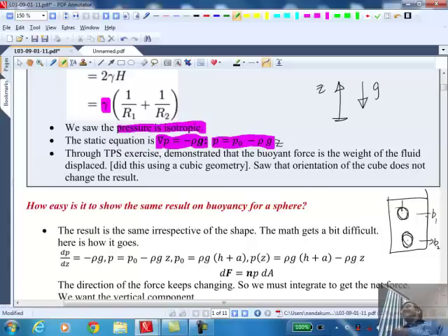So you need to constantly take in and out water to adjust your weight to be equal to the buoyant force. Then you can stay at that level for a while. But at a deeper level, the pressure surrounding that object is going to be much higher. So when you're designing the mechanical shell, you need to worry about at what depth you are. But the buoyant force is going to be essentially the same if you want to achieve neutrally buoyant status. The reason is it is the difference in pressure that matters. The difference in pressure as you go around is what causes the buoyancy force. And that's why it is the same. Any questions?